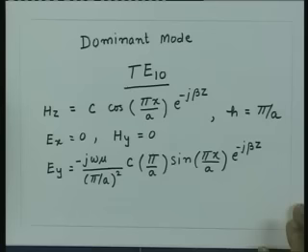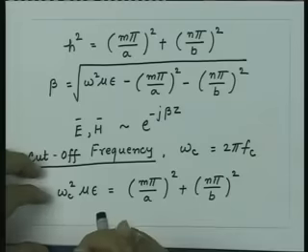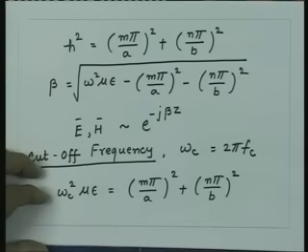So just to conclude, for a rectangular waveguide, the important mode is the transverse electric mode, TE10. That mode we also call the dominant mode, because it has the lowest cutoff frequency, and for this mode, single mode propagation takes place over a certain range of frequencies. So in experiment we make sure that the frequency lies in that range, so there is single mode propagation.